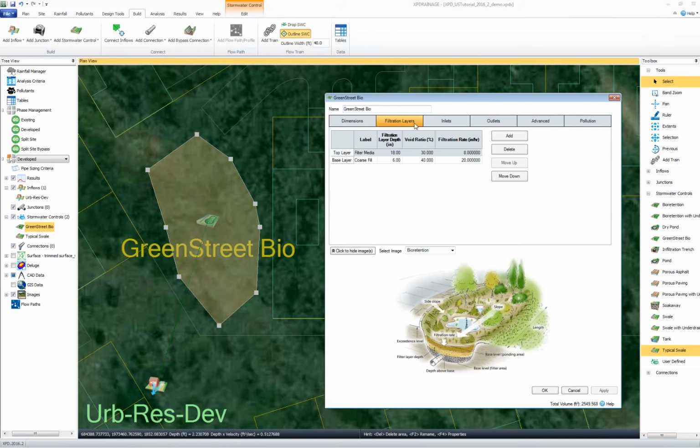For a bioretention system, you probably have filter layers. So the software isn't going to dumb down, I guess there's no other way to put it, these complex shapes. We're not going to take a ponding area with sub-filters, with filter fabric that could be clogged, and make that just an effective bathtub size. Right? We're not going to make that an effective volume. That's not really what's happening.